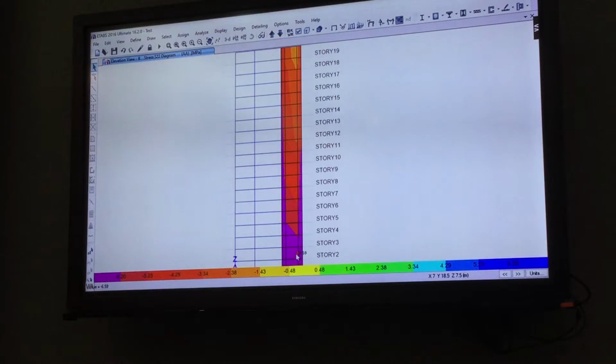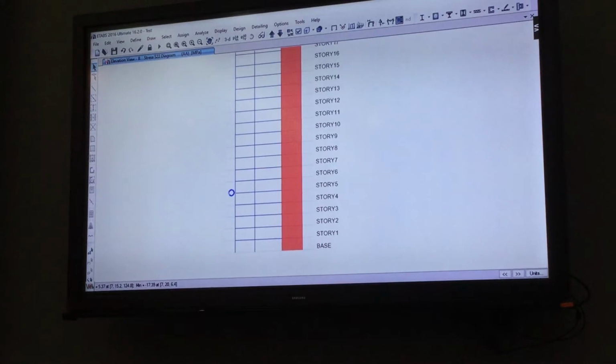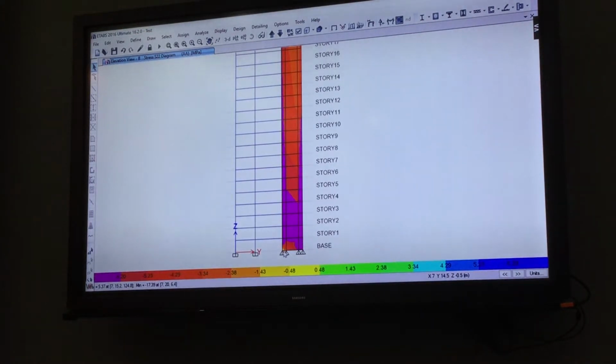Here, in this shear wall, we can see that I limit to 6.2. So you need to provide the special boundary zone from this base to maybe around level 12. Okay, because the stress is exceeding 6.2 megapascal, you have to provide it until this point, until level 12. Then you have to check the boundary zone length from the code equation and provide the confinement. Okay, so you have to decide based on the stress.